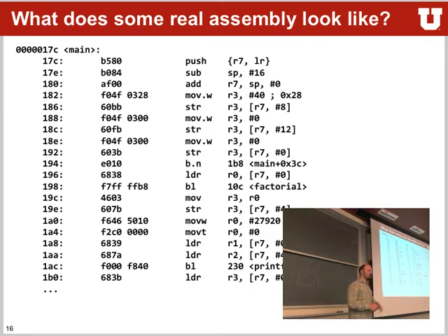We will talk about the stack a little bit later, but basically the stack is where the stack pointer is pointing to. Remember, in one of the registers, the SP, the stack pointer will point somewhere into RAM, and that's your stack. And the push, all it will do is take these two registers and store them at the address where the stack pointer is pointing to. So once we do a push, what happens here with SUB SP, 16?